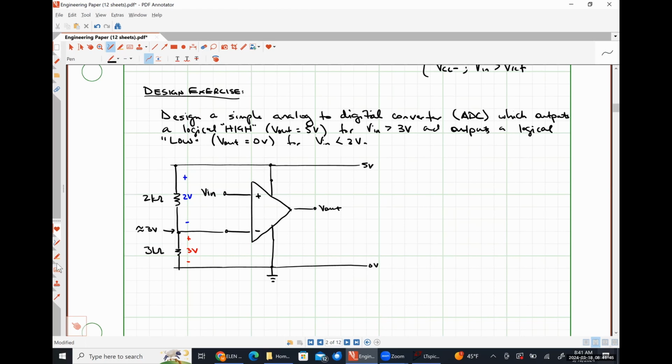I can show you guys how I like to do my op amps and all of that kind of good stuff. So let's get this maybe down here. All right. So the first thing that I'm going to do is I'm going to put my supply voltages in. Okay. So I'm going to have this voltage V1 here. I'm going to put this voltage V2 here. And what I'm going to do is I'm going to wire this in series. And then I'm going to put my ground in the middle.